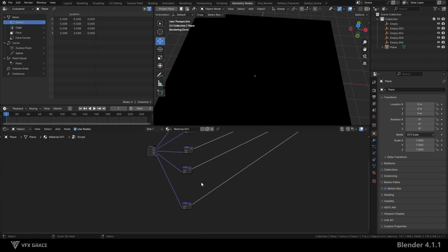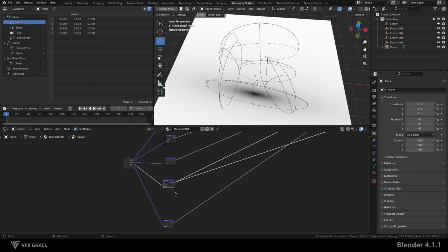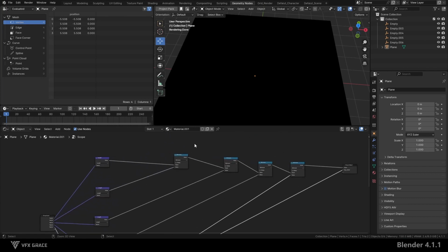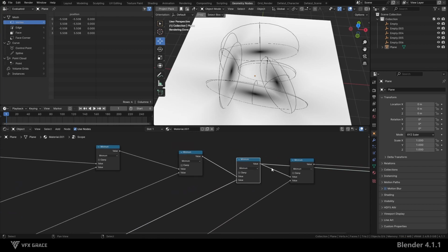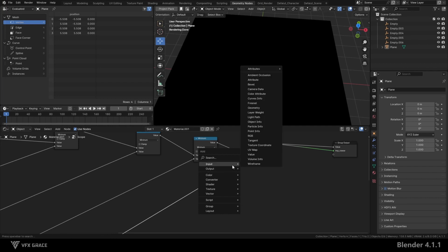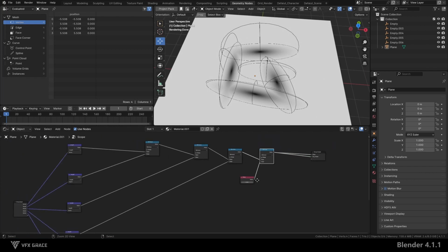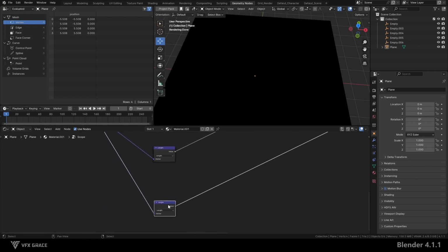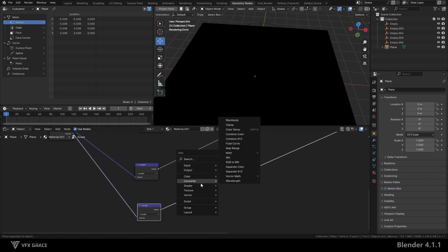Inside the node group, if the external vector port is not connected, the length result will be 0. And since we use the minimum mode to mix several masks, the smallest value is retained. So the entire mask turns black. If we perform a minimum operation with a value of 1, the effect will be normal. So we need to add a logical condition. If the length result is 0, use a value of 1. If the length result is not 0, use the length value.